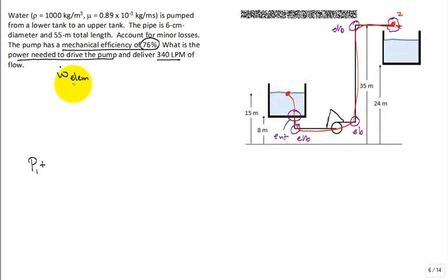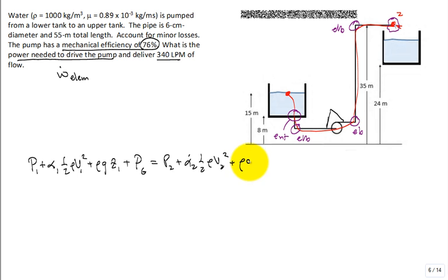It's like the power that an electric motor supplies to the pump. That's going to be greater than what gets into the fluid, the pressure increase in the fluid. But let's write Bernoulli's. So let me go ahead and put the alpha 1, 1/2 rho V1 squared plus rho g Z1 plus any pressure gains because of pumps equal to the pressure at the end plus alpha 2, 1/2 rho V2 squared plus rho g Z2 plus all of those pressure losses. Let's go ahead and write it.